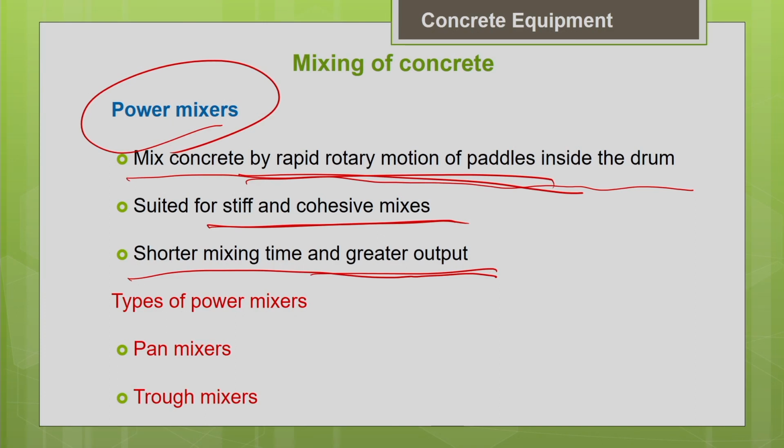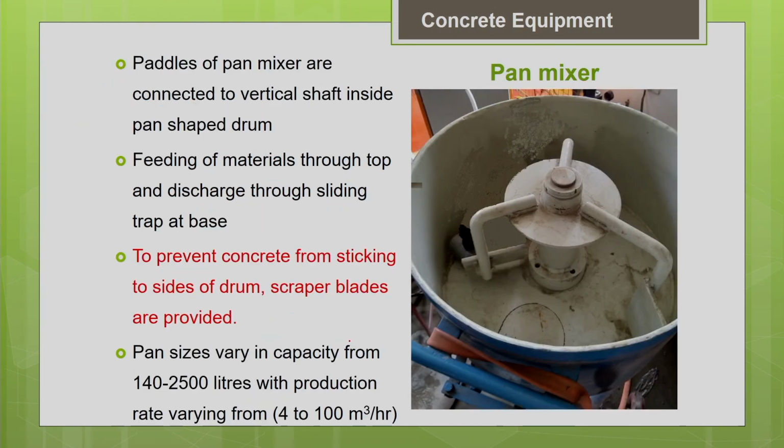When you compare the power mixer with a free fall mixer of the same size, you can see that the productivity of the power mixer is very high because of the rapid rotary motion of the paddles inside. Different configurations are possible with this power mixer. You can go for pan or trough. We are going to see that. First, we are going to discuss the pan mixer.